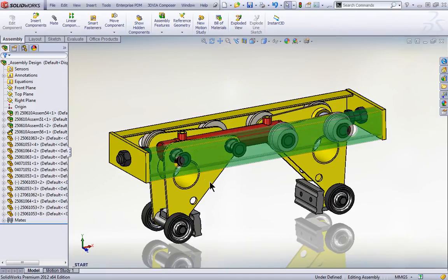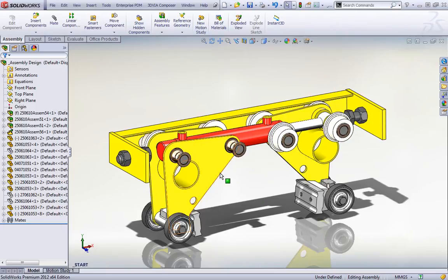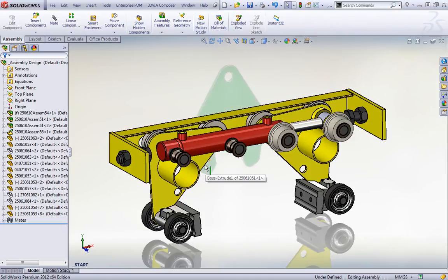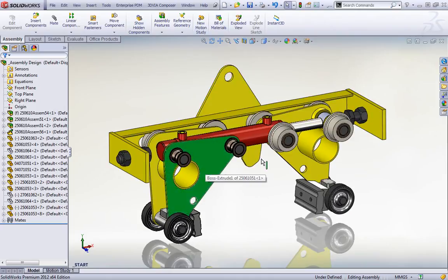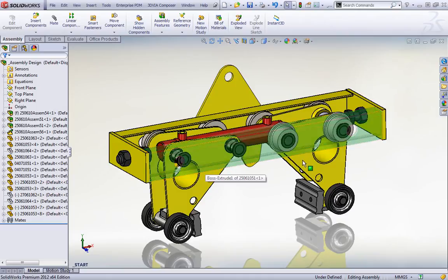In fact, you can actually hold the tab key down, and then it'll go through and actually hide the parts for you when it gets to that particular point in turn. So that's, I think, a huge advantage of time there. So if I go and again shift tab, it'll actually bring the parts back when I'm pointing at them. Alright, so let's go and hide a few more here.